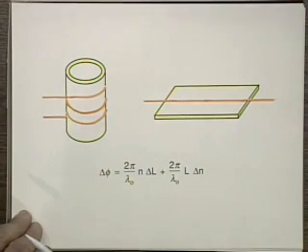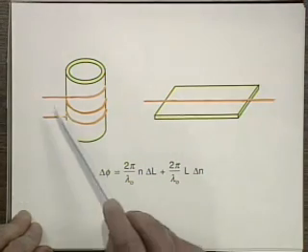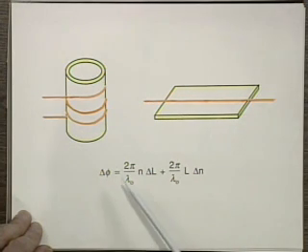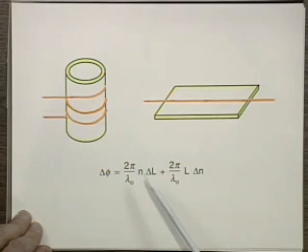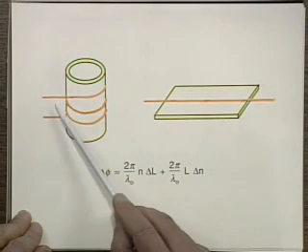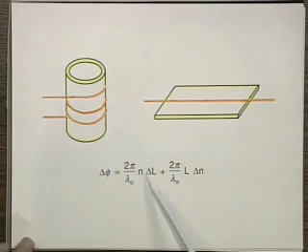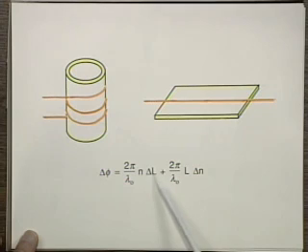All right. And now I wanted to just say again a few words about phase modulators. Now, phase modulators. Well, how do you do that? How do you modulate the phase of the light propagating in the fiber? Well, again, there are many ways, because if we stretch the fiber, if we do something to the fiber, we can change essentially the index in the fiber, or change the physical length of the fiber, and then we get a change in phase, delta phi, that's proportional to either the change in the length of the fiber or the change in the index of the fiber.